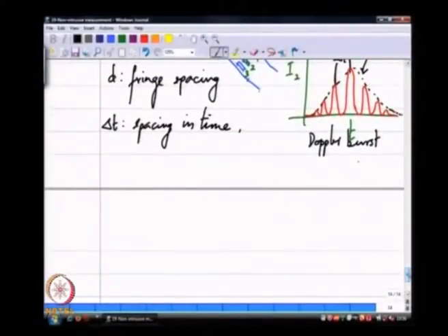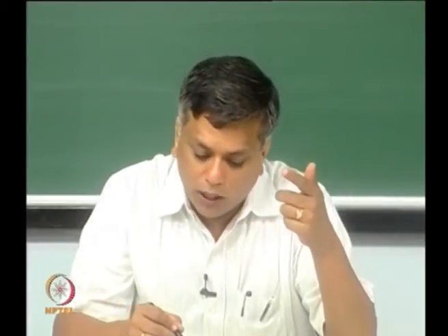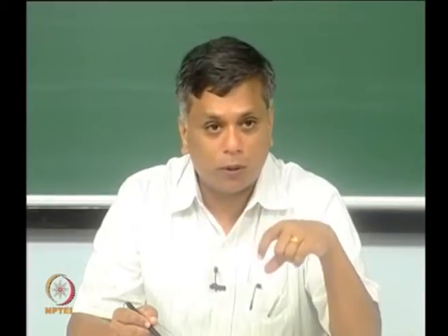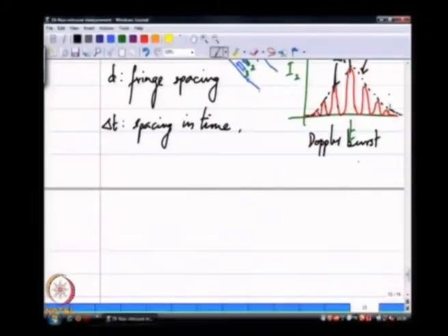But in reality, the way this is done is that one of these Doppler bursts is sampled at some fairly high frequency. So, I have the intensity measured by this detector 2 at various instants of time. If I do a fast Fourier transform of this Doppler burst, there is a particular frequency in time that shows up as a peak frequency.